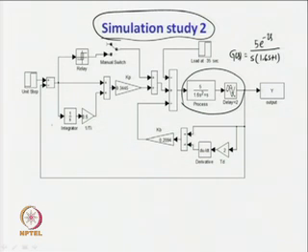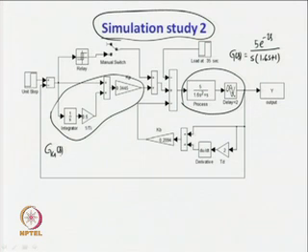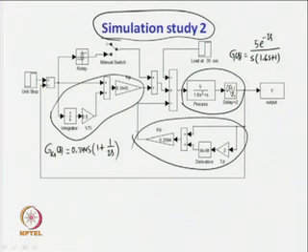Like the earlier case, the integrating process is subjected to a PI controller given by Gc1(s) = 0.3445 times (1 + 1/(2s)), and a PD controller of course, with the transfer function Gc2(s) = 0.2094 times (1 + 2s).